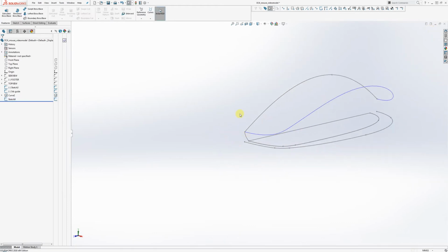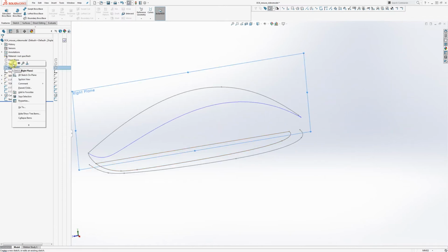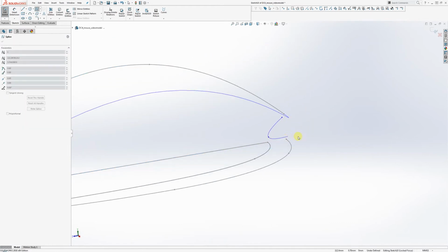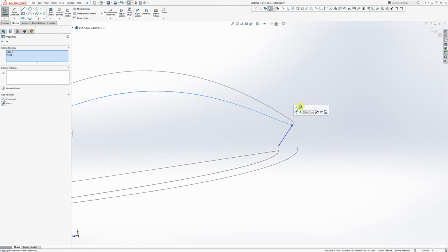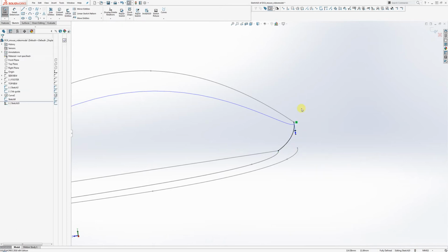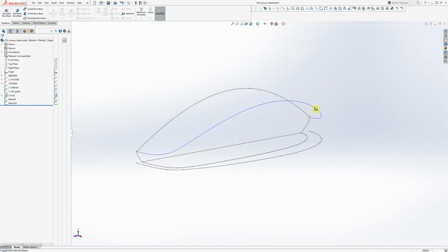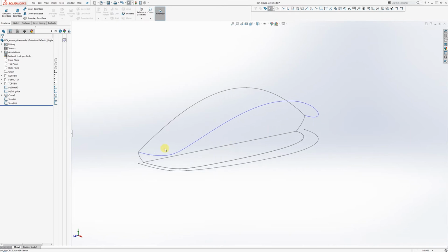Okay, I'm going to do that again with a new sketch on the other side. So I'm going to go to the right view, create a sketch, grab my spline tool, loosely lay down a sketch with 2 points, and then pierce it to the 3D sketch, and then pierce it down to the bottom sketch, and then adjust. Okay. Very good. All right, I'm happy with that. So now I have a four-sided hole here that I can use boundary surface to fill up. Right? This would be one edge, two edge, three edge, four edge, four-sided hole.